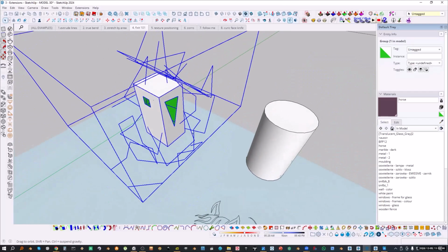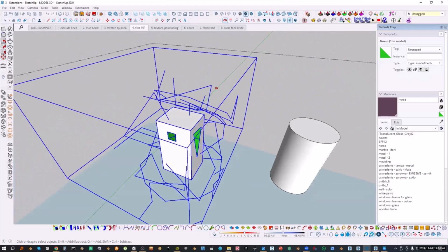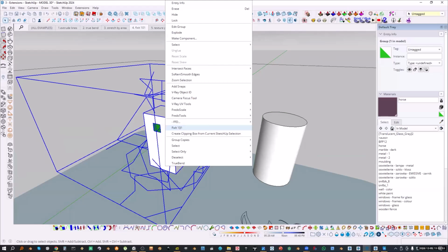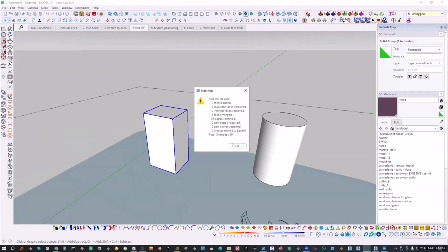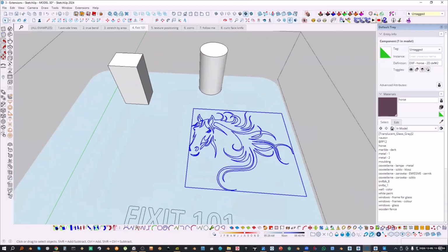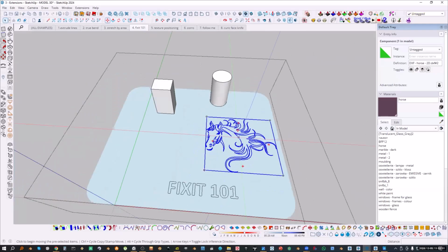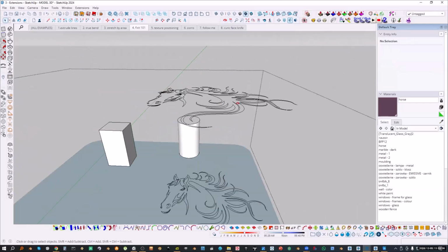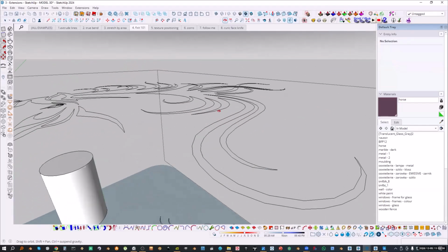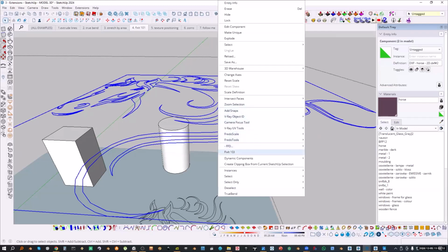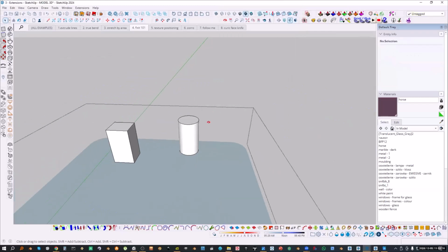And here we have a little bit of a mess with those lines and those holes. I can also right click on that object, Fixit. And now it is fixed. With this one, you have to be careful, because if you decide to use that on a DWG object, which is just flat, just curves and lines, Fixit will actually think that those are just trash geometry, some unwanted pieces, and it will get rid of it completely.